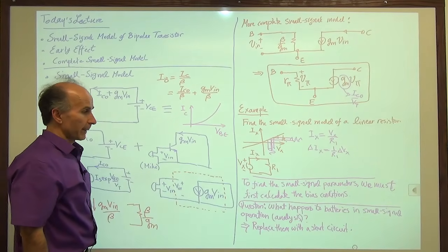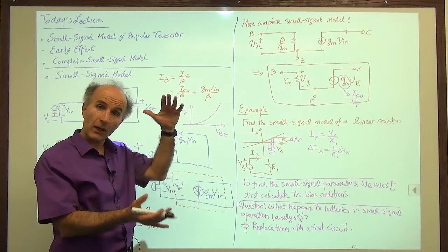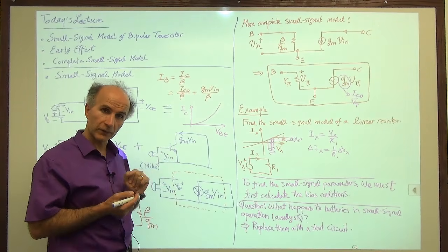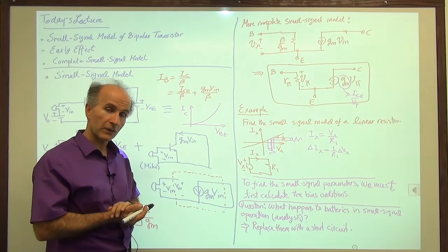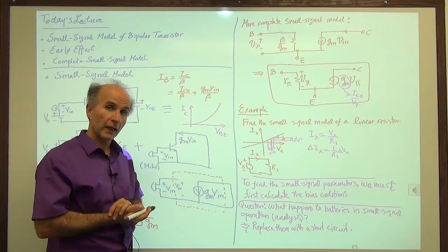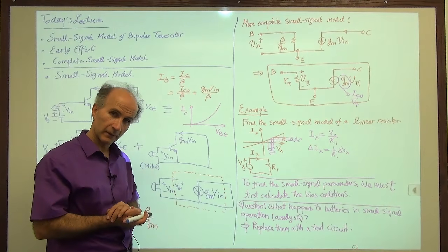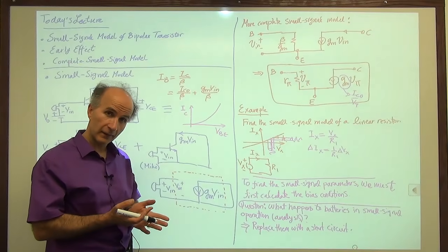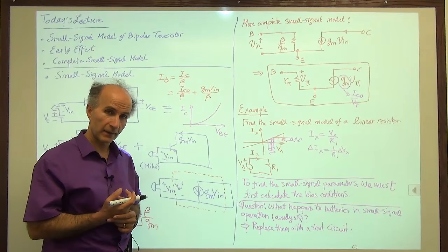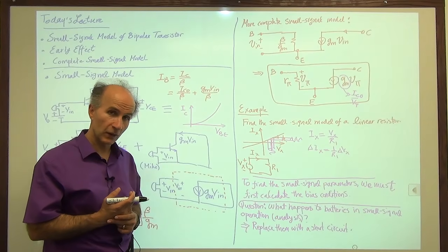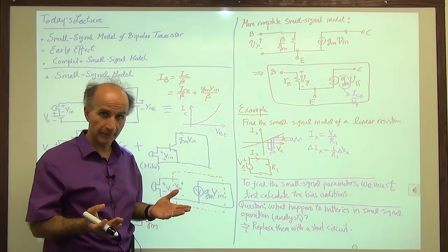So, for example, if we have some sort of circuit that has a power supply, the power supply is a constant voltage. So that constant voltage is always set to 0. Now, sometime later, we might see current sources as well in our circuits that are constant. If a current source is constant, again, for small signal operation and analysis, its value should be set to 0 because it doesn't have any perturbation, it doesn't change with time.